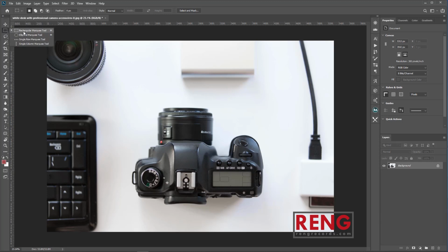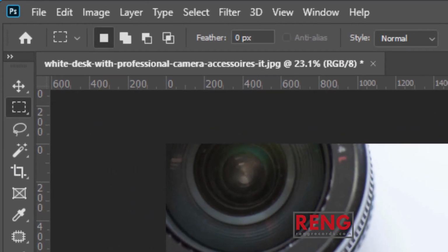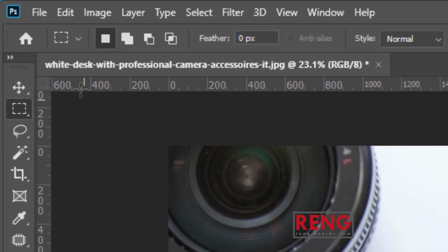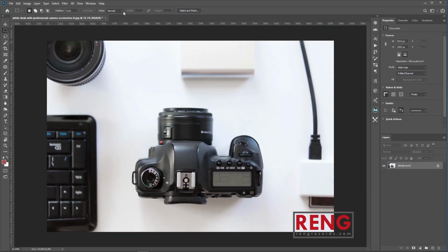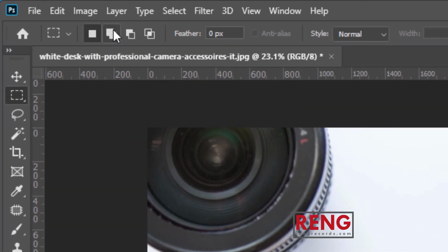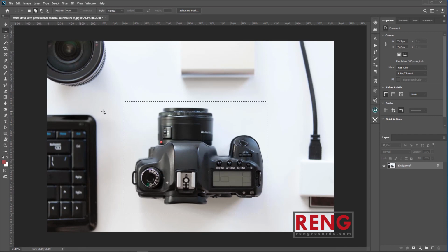Whenever you select one of the tools from the toolbar, the settings bar under the main menu for the same tool is activated. If you want to select another range while using the selection tool, first exit the selection mode. To be able to go to another area after selecting the first area, from the option toolbar, you can click on Add to Selection as shown below. Click, or hold down the Shift key during the next selection. In the figure below, the two selected areas are grouped together.